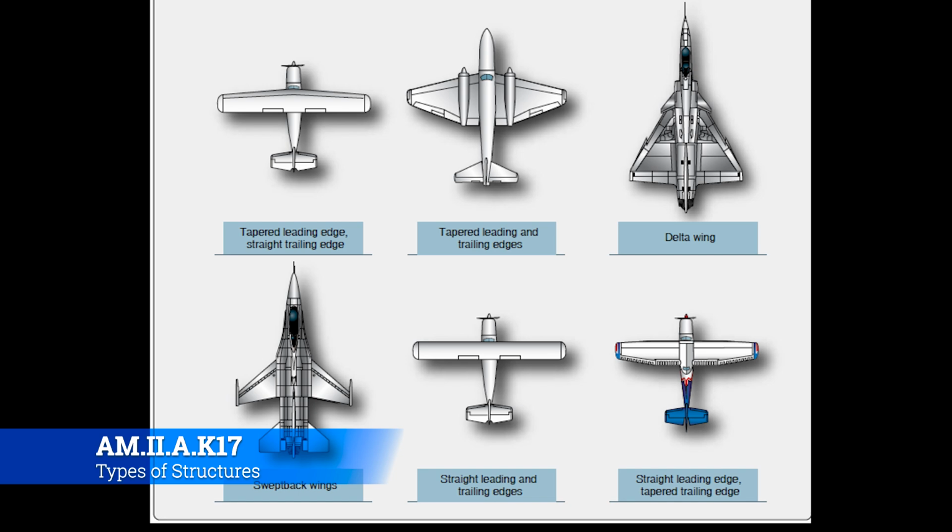The advantage those wings also give it is that it allows it to be nimble. So it can do snap rolls, whereas the airplane above it on the graphic and to its right won't do that. They'll still roll, but they're going to roll a lot slower because they have to push that big wing through the air with a lot less power on the engine.